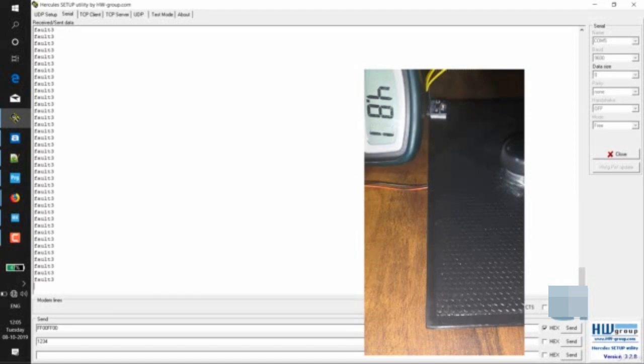As you can see over here, we are judging the state of the machine via sensors without establishing any electrical contact to the machine. That's why the solution will be more reliable and long lasting. I have trained the neural network on my setup. Vibration patterns may vary in your case. You can use the same neural network, but you need to train it on your setup to get the maximum accuracy.